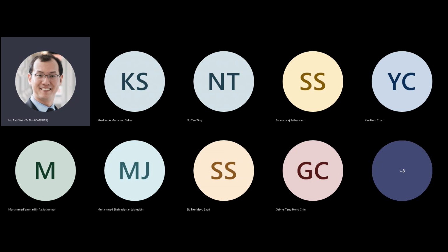The electrons are being attracted by the potential difference, but because there are nearby electrons that are meandering, an electron will come into close contact with another electron and get repulsed, and then it's just moving and meandering in a larger path. So the average time it takes to cross here is actually higher. So this is modeled as a reduction in the mobility of the electrons, the carriers in this device. So temperature also has an effect on the mobility.